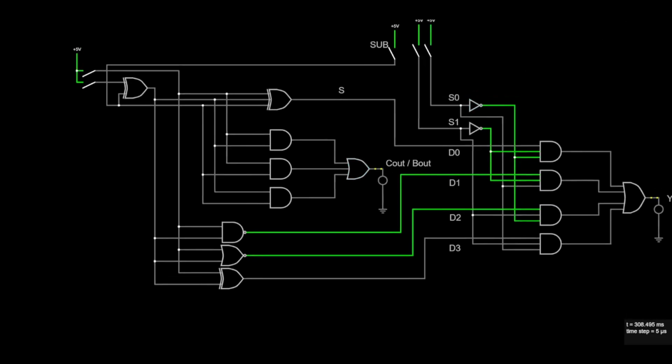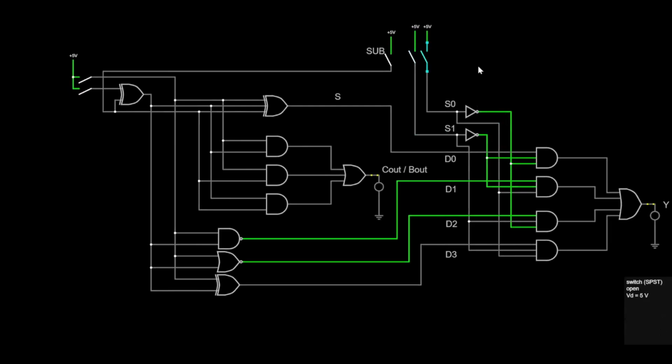If you see, there's the selectors that don't go anywhere, but normally in a CPU you would see the control logic, which actually tells the ALU what operation is being performed. And so the operations are add, there's also usually a no op, meaning don't do anything. It depends on the architecture, but there can be a NAND, a NOR, or an exclusive OR for our case. And these are a bunch of different operations we can perform.